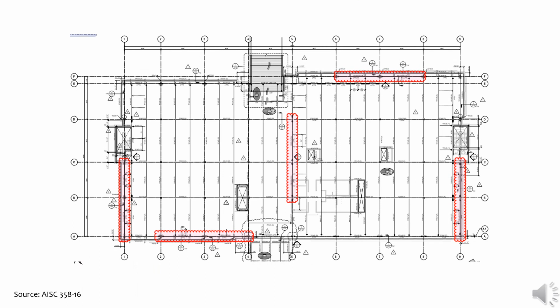With the side plate technology, stiffer moment frames can be modeled. This typically reduces the number of moment connections by 20 to 30% compared to the conventional moment frame buildings. You will see in this framing plan that only a pair of two-bay SMFs is required along the x-axis and three two-bay SMFs are required along the y. Additionally, the increased stiffness allows the design team to minimize the beam and the column weight by 15 to 25% of the lateral steel tonnage.